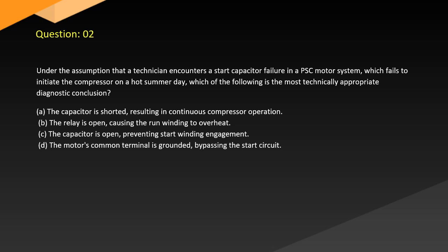Question 2. Under the assumption that a technician encounters a start capacitor failure in a single-phase system, which fails to initiate the compressor on a hot summer day, which of the following is the most technically appropriate diagnostic conclusion? A. The capacitor is shorted, resulting in continuous compressor operation. B. The relay is open, causing the run winding to overheat. C. The capacitor is open, preventing start winding engagement. D. The motor's common terminal is grounded, bypassing the start circuit.